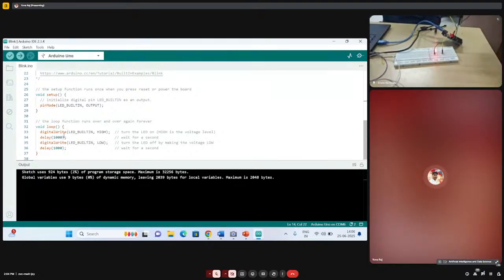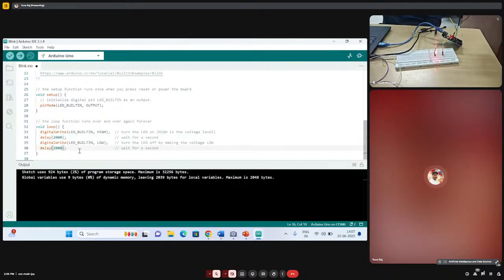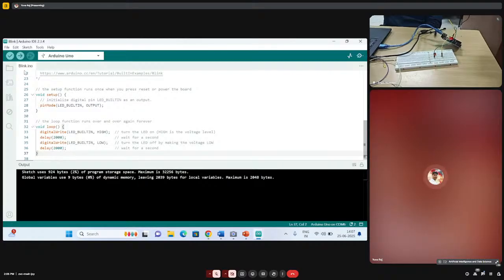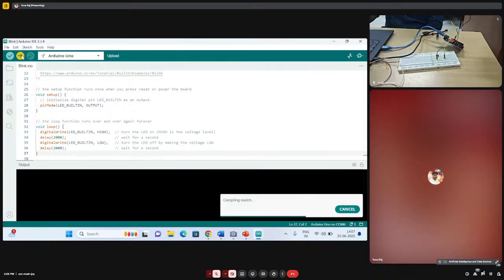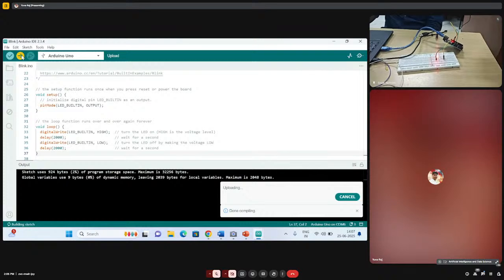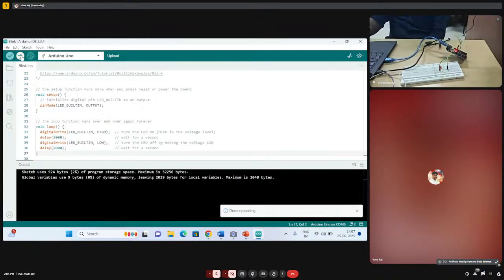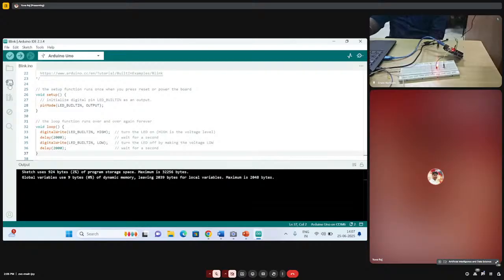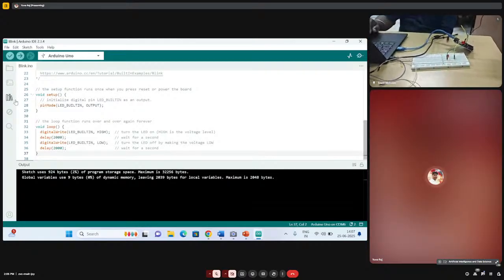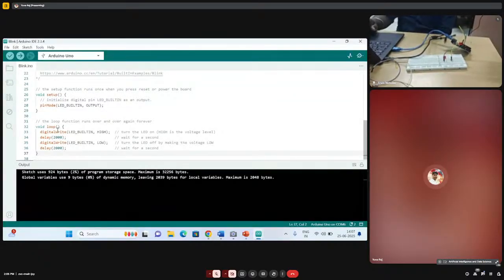Likewise, the delay time is important. Whichever you need, you can change it. For example, I will change it to a delay time of 2000 and 2000. Again, I will upload the program. So see the difference. After 2 seconds only, the light will glow on. So the delay depends upon the delay time only, and the light will glow accordingly.